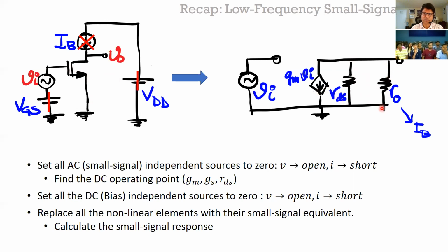Then I have drawn this, actually, sorry, maybe I shouldn't have said that there is no R0. So this IB, when you make it 0, it still has a small signal element to it, which is R0 from V out to ground, because this is shorted here. So you essentially get the output impedance of this transistor in parallel with the output impedance of the current source, and that's your total output impedance. And I think when you do the common source example, it'll be much clearer. So that's a quick recap on creating small signal models from a large signal equivalent.